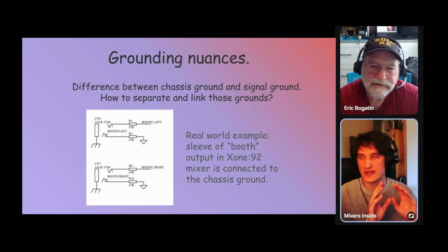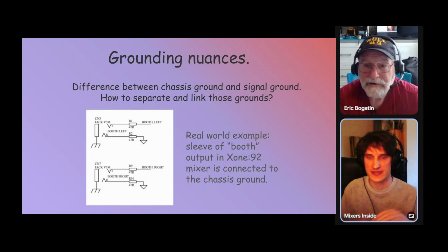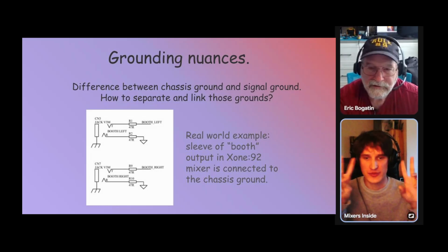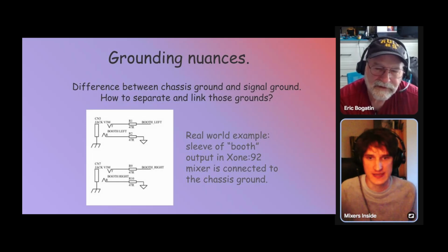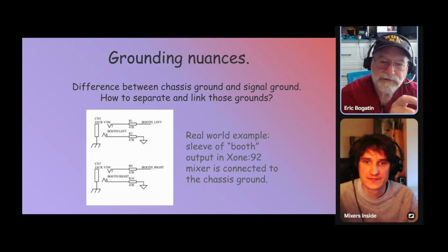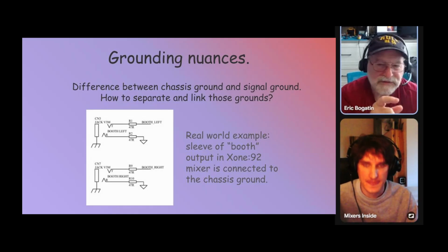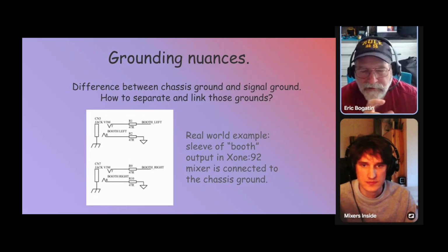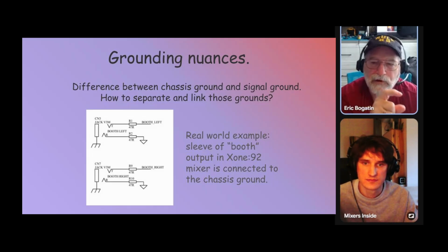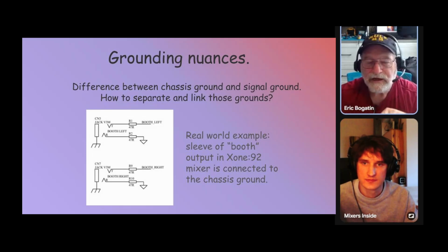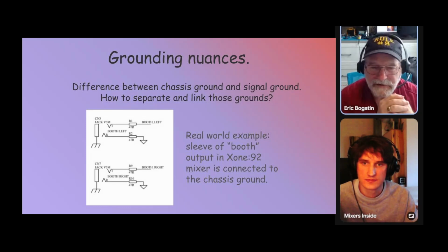The signal is just not a reference to this ground, and there is no potential dirt. Yes, it goes by its own. It's a reference to the original source, because at that source, whatever sensor you're using for the microphone or the pickup, it's guaranteed a differential signal. There's signal and it's returned locally, and that's what you want to carry along with it, so you don't pollute that low side of the signal. You don't pollute it with noise from currents from other places.